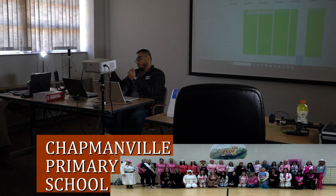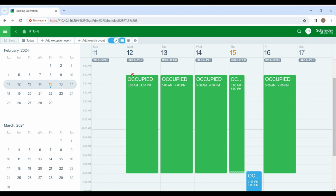But it's not going to shut down as soon as it gets below 78. It will track the actual occupancy set point, and once it's satisfied, then it will shut down. So you're not looking at 2 degrees and the unit shutting down. We're talking about 7 degrees, maybe an hour of operation, maybe more, and with that, you already have a 5 a.m. schedule start. The optimal start will be useless at that point in time.